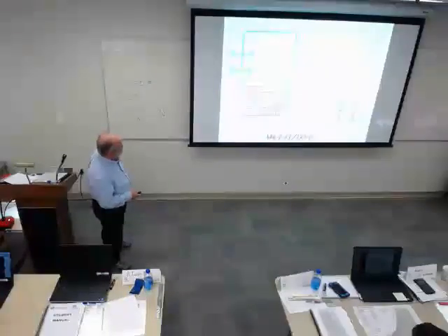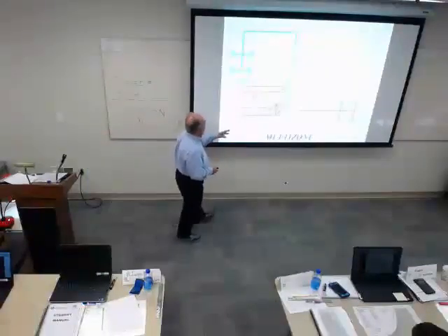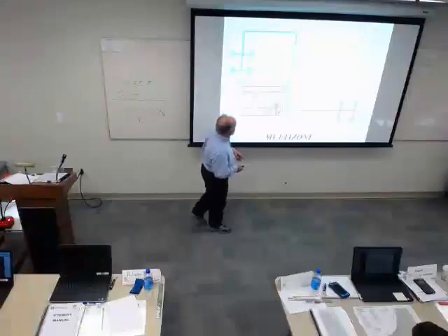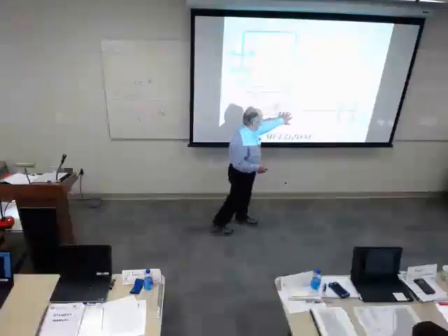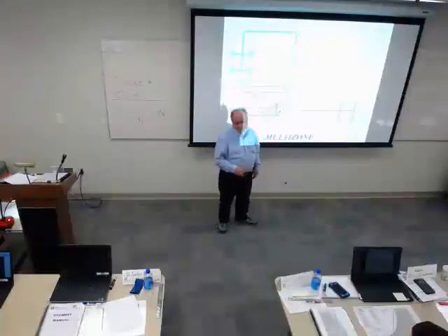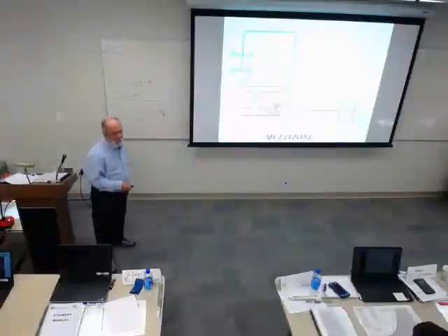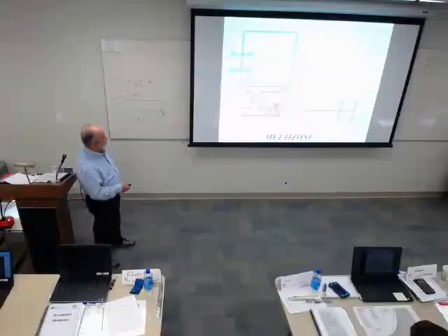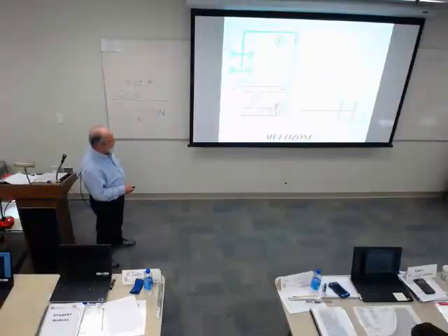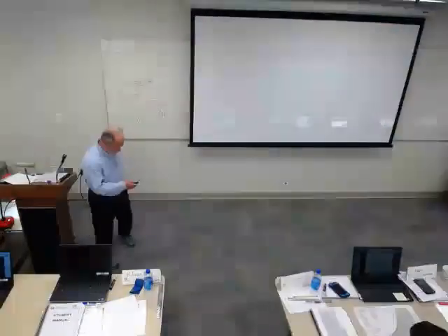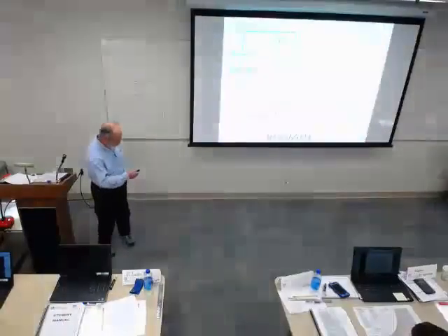Okay, so here we have one. We've got several zones coming off this air handling unit, and for the designer, the key thing is that all these pressure drops out the diffusers have to be the same. Otherwise, it's almost impossible to get it right. So we've got temperatures that control the dampers.